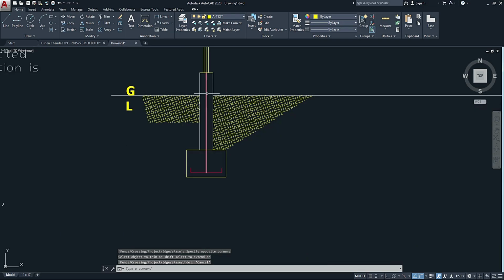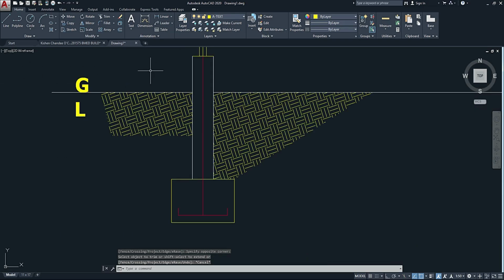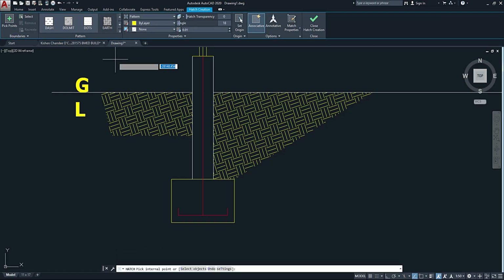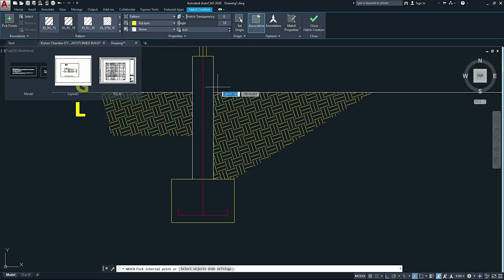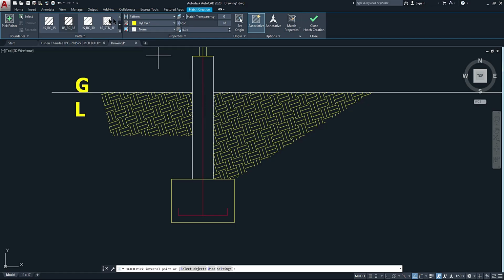Now the only other thing that you can do here is hatch inside the block wall. I'm going to show you the one that we're going to be using, one of these here, and you simply hatch. Let me double check, use this one, hatch that one and that one there, and we can change the scale.